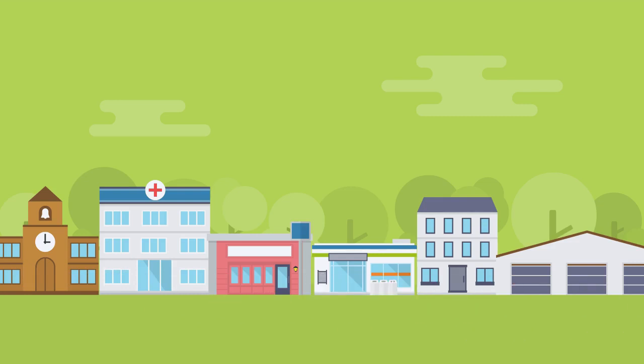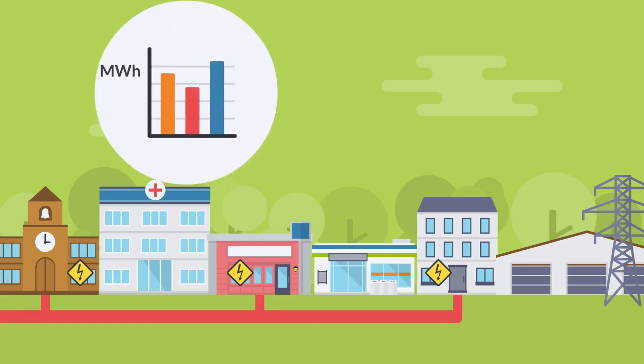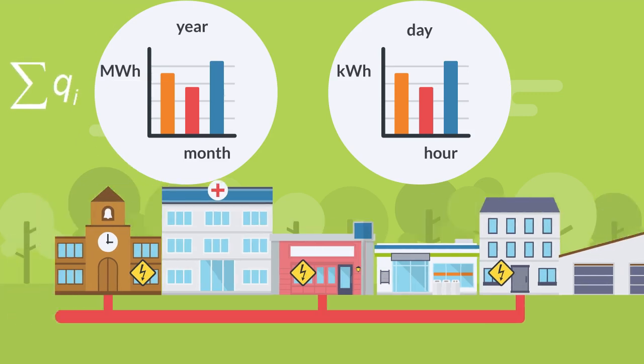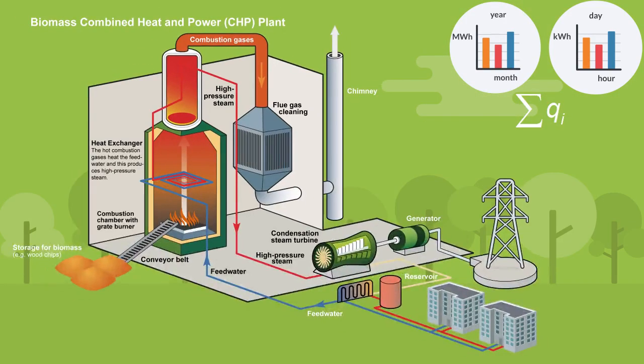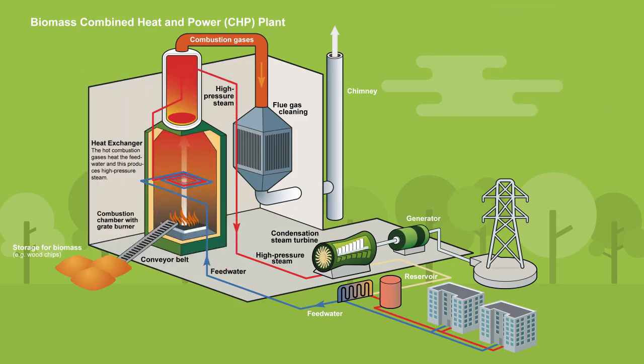Take a decision on the energy services: heat supply, electricity, or a combination of heat and electricity. Calculate the energy demand curves for every month along the year, for every hour along the day. Calculate the amount of energy to be supplied for 1 year. Using the demand curves, take a decision about the system capacity, that is, the power of the boiler or combination of boilers. The final decision will be taken after the selection of commercially available equipment.